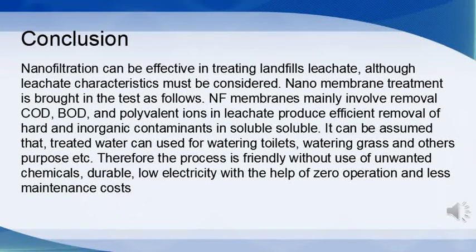So, the conclusion is nanofiltration can be effective in treating landfill leachate, although leachate characteristics must be considered. Nanomembrane treatment is summarized as follows. Nanofiltration membrane mainly involves removal of COD, BOD, and polyvalent ions in leachate, producing efficient removal of hard and inorganic insoluble contaminants.